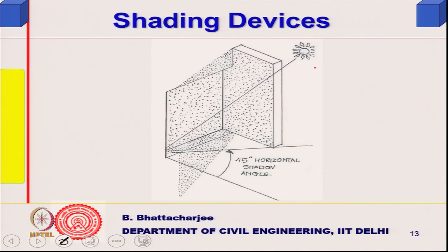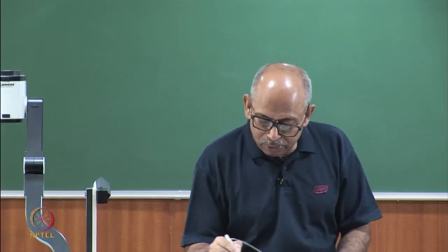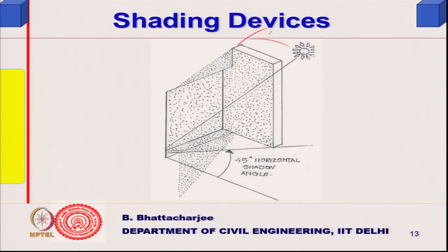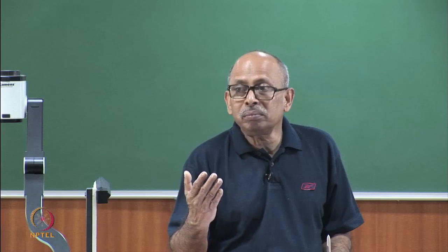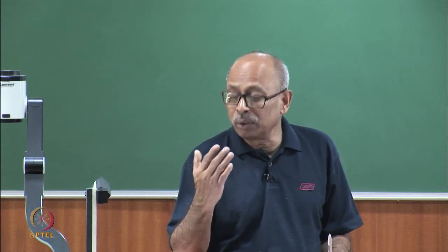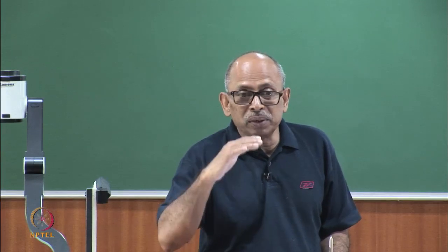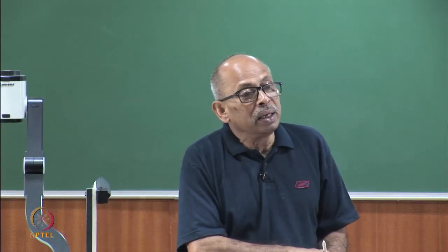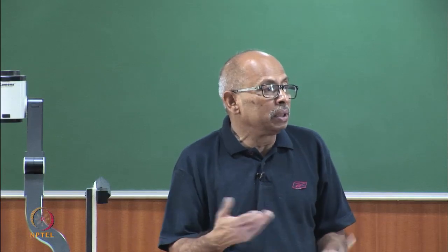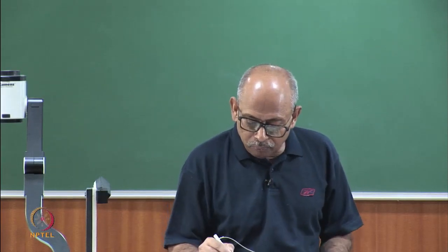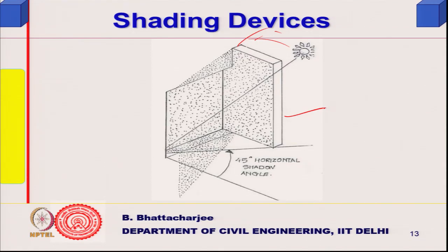Early in the morning or in the evening, it should block from this side, right, it should block from this side, for south facing surfaces in the northern hemisphere, or east facing surfaces you can put it on. An east facing surface will receive sun, but the altitude angle of the sun is lower, so you will have to see how you work it out.